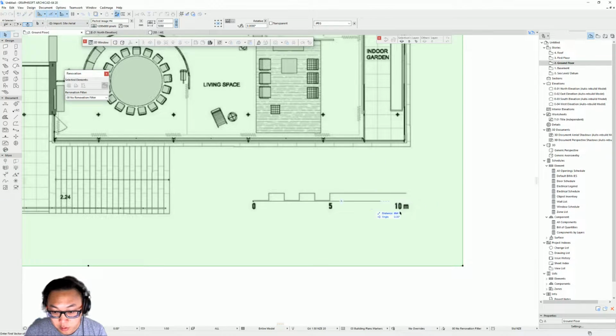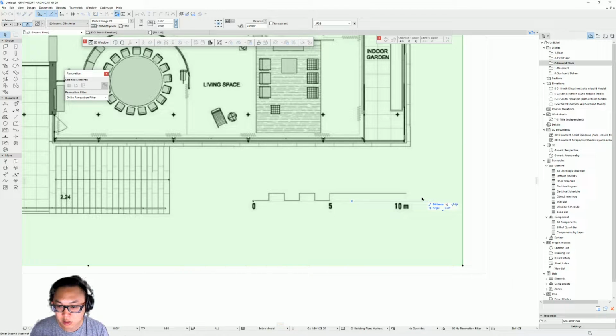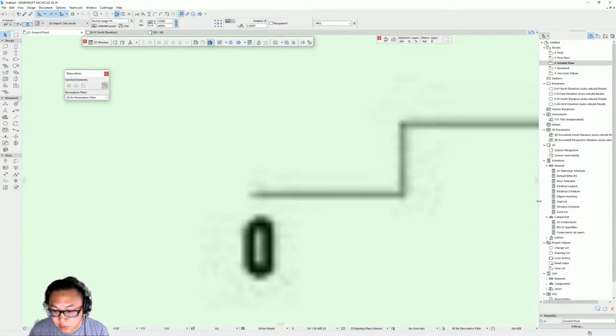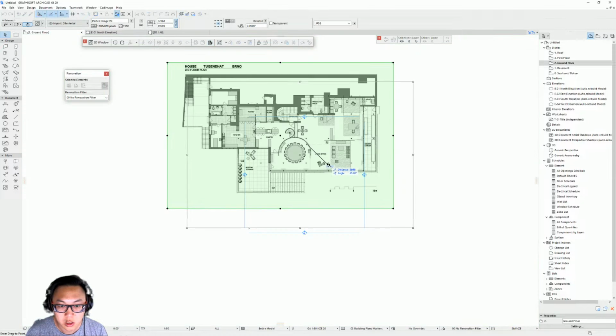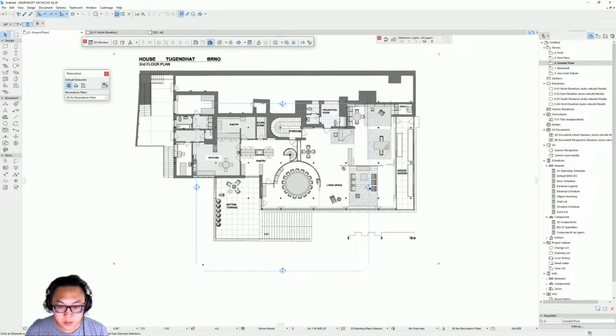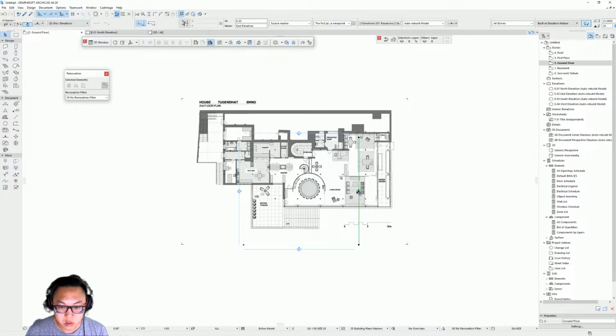If you hold Shift, it will keep the line straight to here, and then here you can resize. So here the distance is highlighted, and you can just type in 10,000 because mine is set in millimeters right now, and then press OK. So now it resized the house. Next steps, well, I don't really need the document elevations, so I can just hide them.